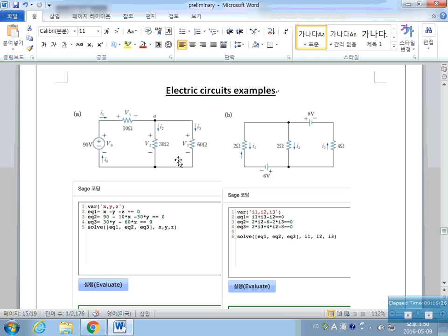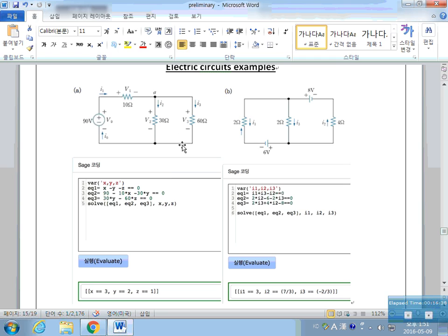So the first thing we can do is apply something called Kirchhoff's law. That means that it's kind of an energy preservation law. So at each point, the currents that are coming in are equal to the currents that are going out. We can denote I1 here as x, and I2 as y, and I3 as z. So we know that I1, which is x, equals y plus z. So x minus y minus z equals 0. This defines one equation. We need 3 equations to find these 3 unknowns.